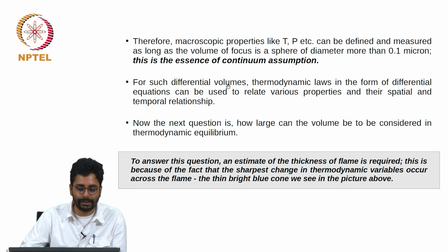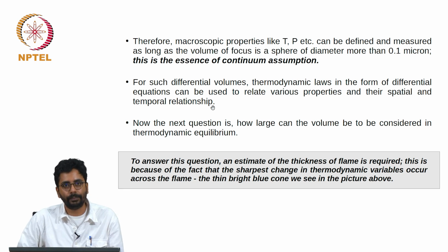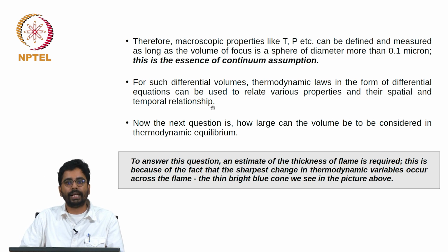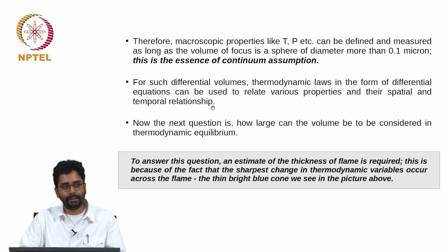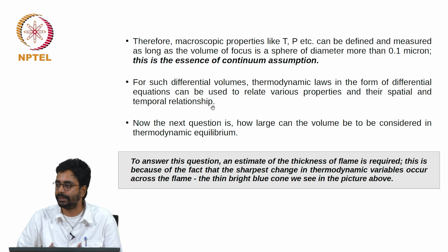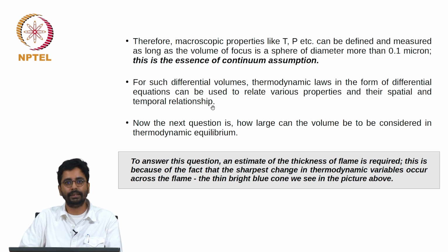This in essence is the continuum assumption, and for such differential volumes, thermodynamic laws in the form of differential equations can be used to relate various properties and their spatial and temporal relationships, which we call the Navier-Stokes equation, which we use for simulating flows and reactions through different combustion systems.